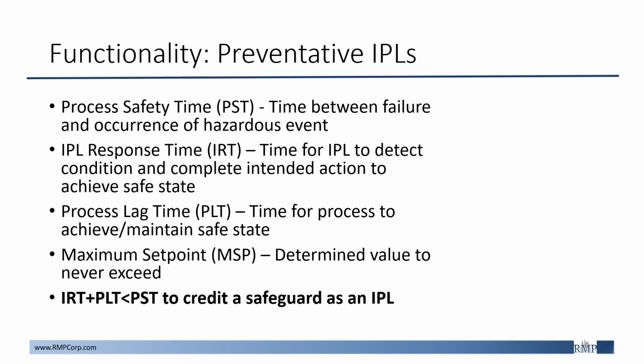And this is an important timeline to consider when developing your overall set point for the IPL, because we want to make sure that we allow for an adequate amount of time for your operator response to act prior to that hazardous event developing. The set point can also be referred to as a maximum set point, which would allow for a sufficient time for this diagnosis and the corrective action from your operations folks.